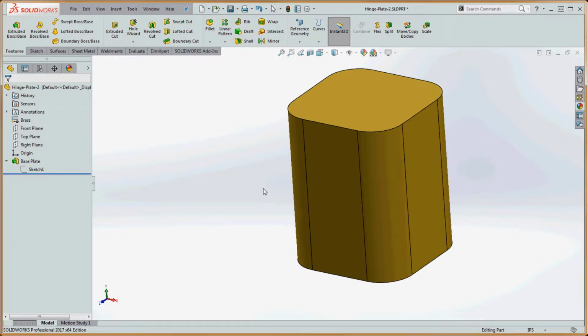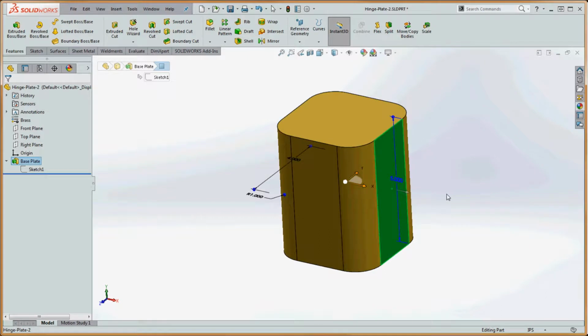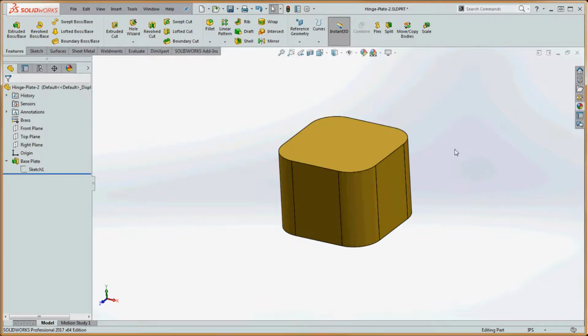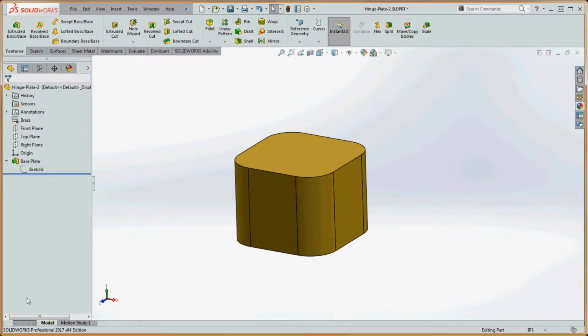So now you can see what that looks like. And if you want to make modifications to this yet another way, if you were to click on the model a little bit, on any surface on that model, and sometimes you have to spin it, the dimensions come up which actually define that model. So if you want to change that 4-inch dimension on the side, which is going to change the other 4-inch dimension up here, which is going to be equal to it, we can do that. Our fillet's going to be 1 inch. We can change that too. The height's going to be 5 inches. The height's in blue, which shows you that it's part of the extrude. And just for the final, let's go ahead and click on that, and we're going to make that 3. So something is a little bit more squarish. So that's a modification to our feature.